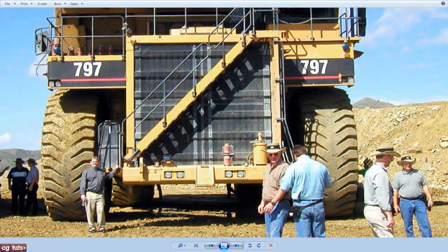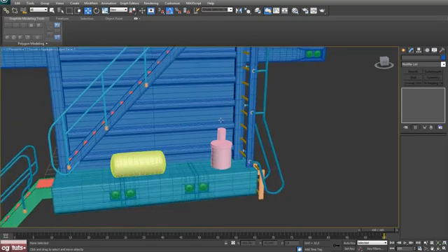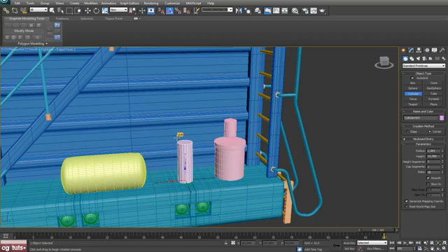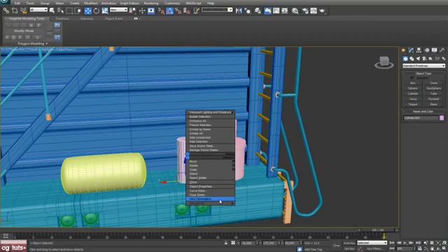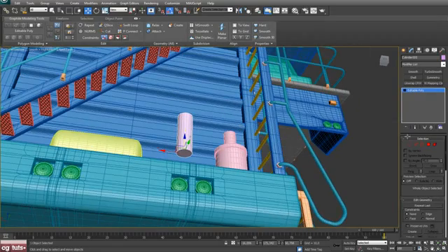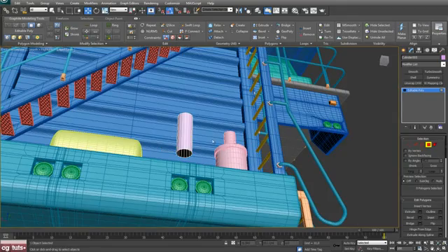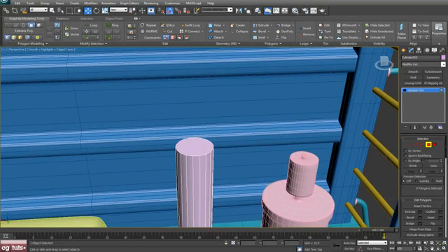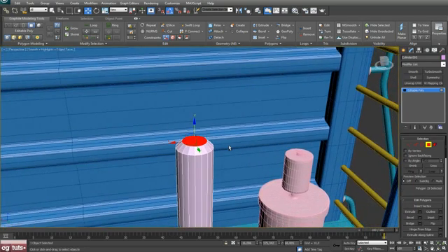And we can create this part here, so this piece, and zoom in. Let's make again one cylinder, something like that. Convert that to editable poly. Delete this bottom polygon. Okay, and select this here and hit extrude. 2 will be okay. And now scale that down and push that, something like that. Okay.